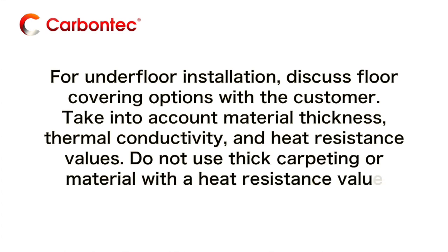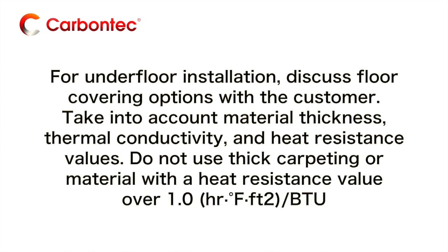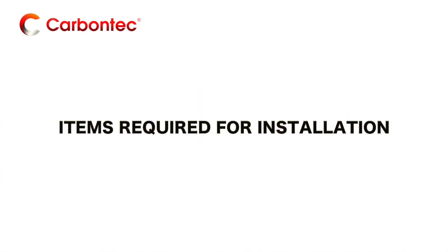For underfloor installation, discuss floor covering options with the customer. Take into account material thickness, thermal conductivity, and heat resistance values. Please note, no thick carpeting or material with a heat resistance value over 1.0. Now that you have discussed and planned the installation, let's go over the items required for installation.